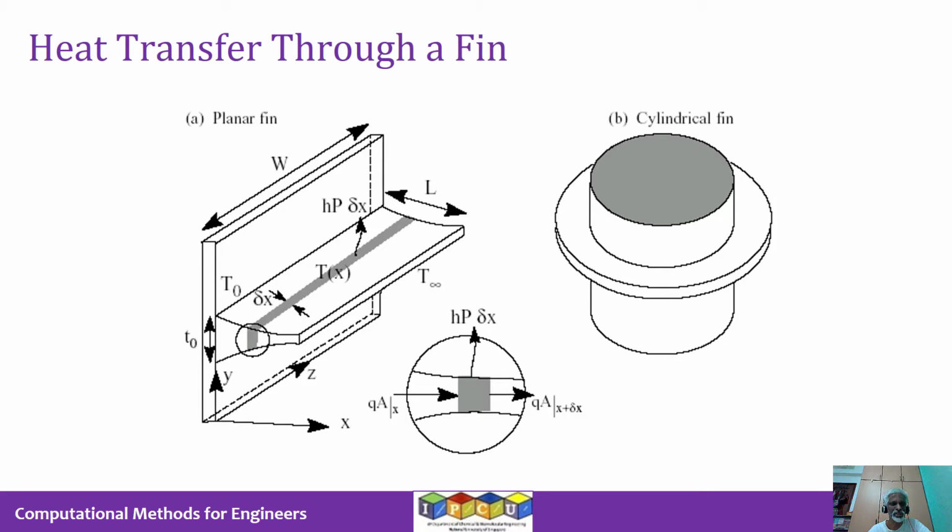With that introduction, let me just mention about fins, right? So basically, heat transfer occurs across surfaces. If you have a hot fluid or a hot object that needs to transfer heat to a cooler body, then a certain heat exchange area is required. So the heat transfer is proportional to the area available for heat transfer. More the area, more the heat transfer. So to enhance the efficiency of heat transfer, what people do is they design fins.